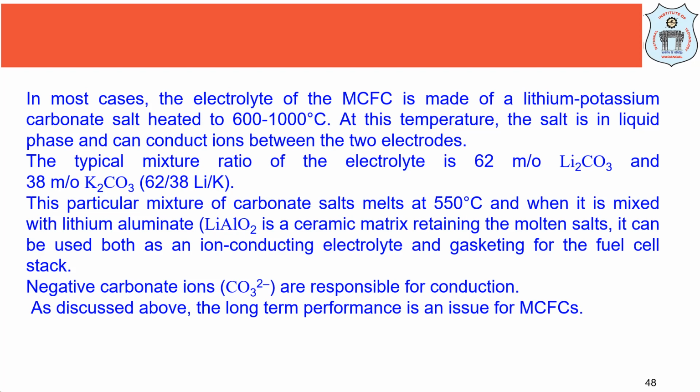This particular mixture of carbonate salt melts at 550 degrees Celsius when you use the eutectic mixture of 62 to 38 mole percentage of lithium carbonate and potassium carbonate. When you use lithium carbonate and sodium carbonate, each salt will melt at its own melting point, and accordingly we have to use it.